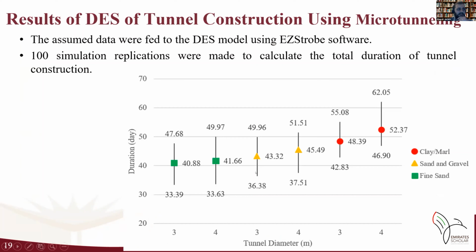In this figure, we can see the results of the simulation for tunnel construction using microtunneling. For instance, it will take about 41 working days to build a 4 meter diameter tunnel in fine sand.